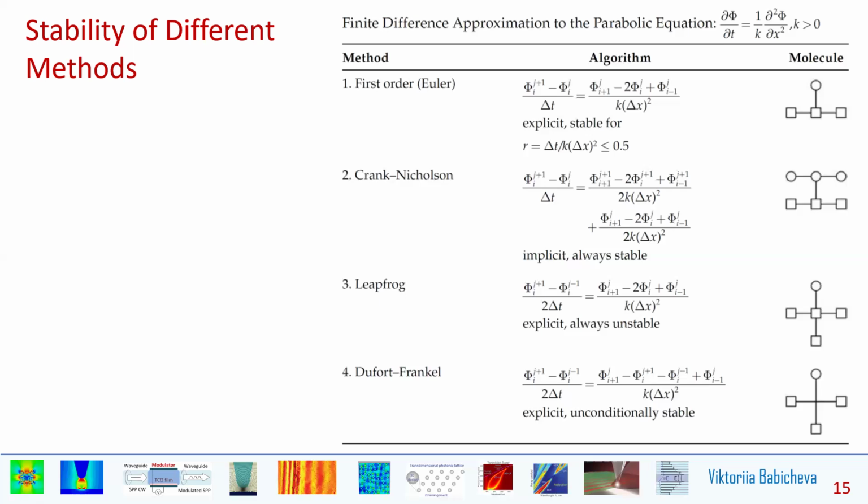It's not correct to assume that the unconditionally stable property implies a physically realistic solution will always be provided. So we can't assume that the solution is accurate no matter how large the time step is. The stability of the numerical method only ensures that the solution will eventually decay out, but it does not guarantee a physically plausible solution.